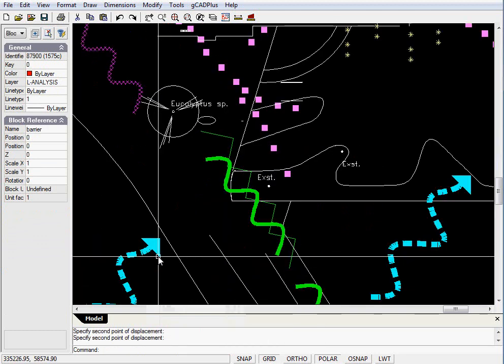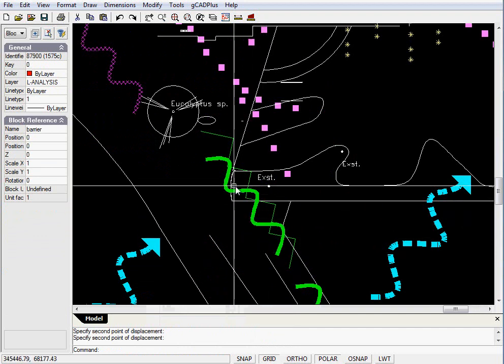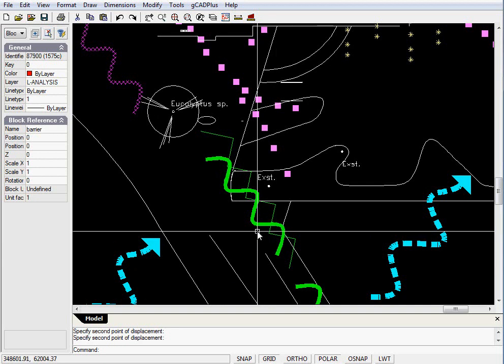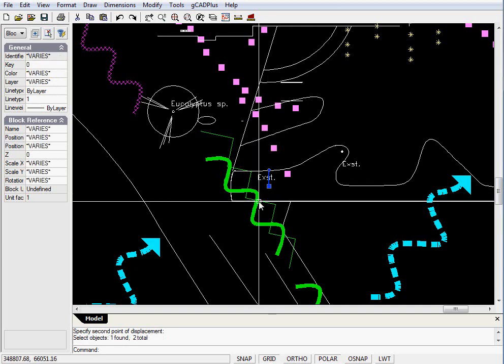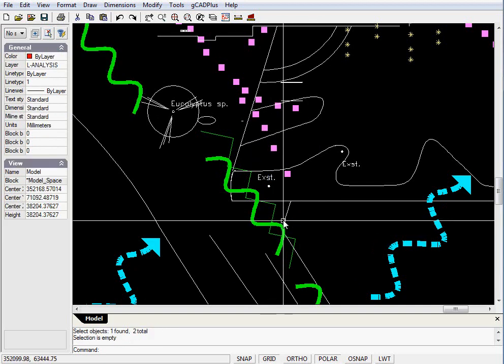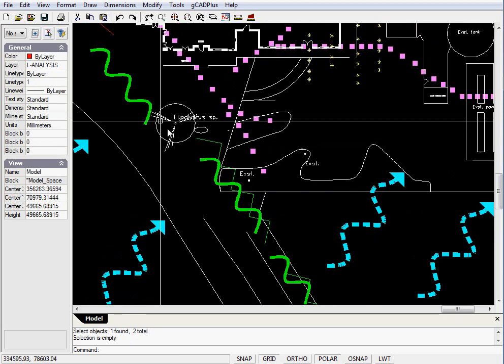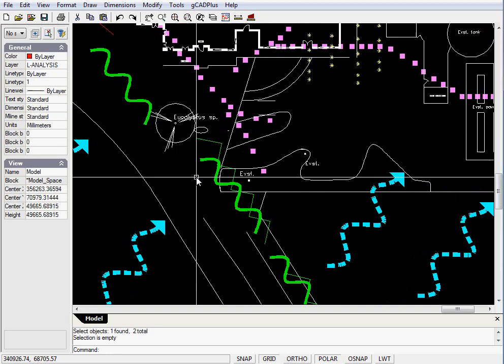So the combination of that will be a solid barrier, or you might want to use a line type with it, but I think a solid barrier works reasonably well. So we would then clean up some of these other lines. There was an existing eucalypt there, and we're just indicating to us in a concept sense we need some heavier planting. And I hope you agree that that type of curve fitting in a polyline with a width adds some interesting graphic elements to this concept diagram.